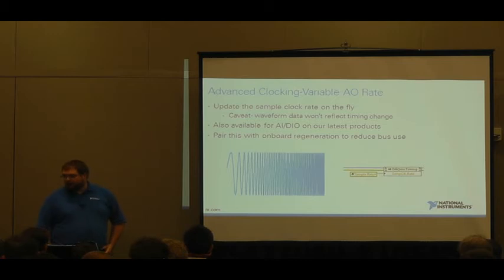And then we can pair this with onboard regeneration. That way we load our signal onto the buffer once, and we continue to generate it, and we don't have to waste bus traffic, and we don't have to waste energy recalculating our signal. We can just continue clocking it out at new rates.